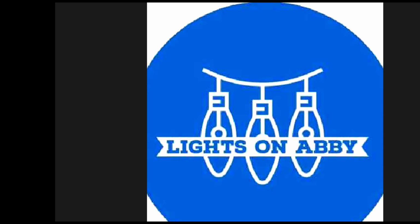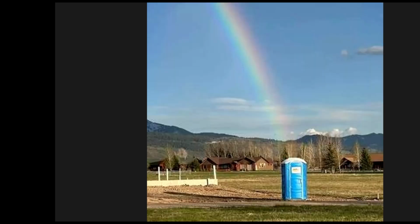Any comments by anybody on that? Red seems to be, so like if you're running out of power, red can possibly light what the other colors can't. Yeah, so red LED does consume a little bit less power than some of the other colors to generate it, but it's not enough to alter your calculations. That's why sometimes when you're running white and starting to run out, the pixels might start to pink up a little bit. Depends on the specific pixel. But yeah, red is a little bit lower current draw as far as just an LED specifically, but it's negligible when you're doing your math from your calculations and planning.